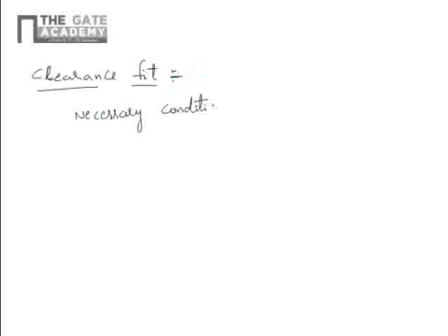So clearance fit. The clearance fit is formed when the lower limit of the hole is greater than the upper limit of the shaft. For clearance fit, the basic and necessary condition is lower limit of hole is greater than upper limit of shaft.